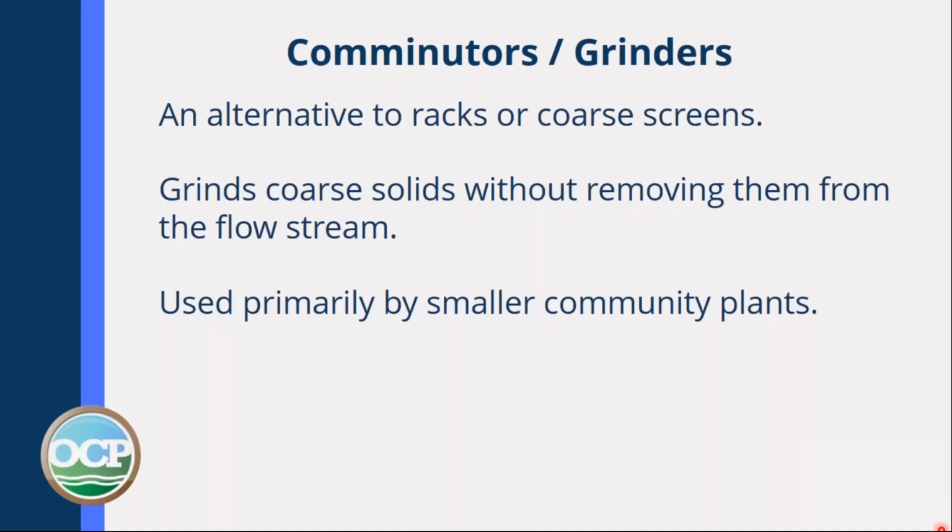The third way of getting rid of material you don't want to get into the wastewater treatment system is grinders, or what we call comminutors. And there are lots of videos out there. I think one's called a muffin monster. You can just check it out on YouTube. You can throw all sorts of things in there and it will just chew it up into very, very small pieces.